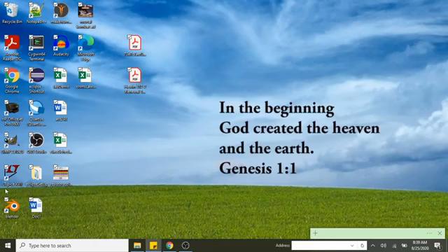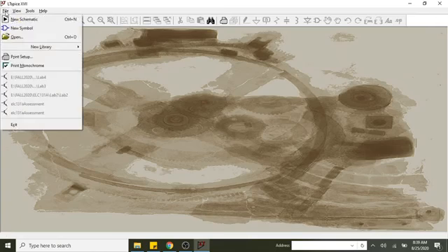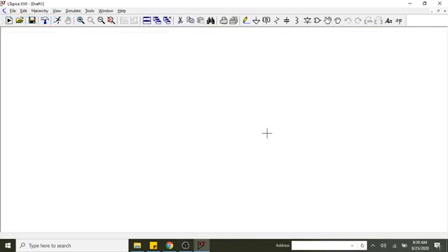Okay, so this is what it looks like, LTspice XVII. So we'll double click on that. And when it comes up, you've got this just blank canvas here. And at this point, we need to actually create a new schematic. So we'll go File, New Schematic. And now this becomes a different looking background. So up here you can see that it's called Draft 1. So that's what it gives it by default.